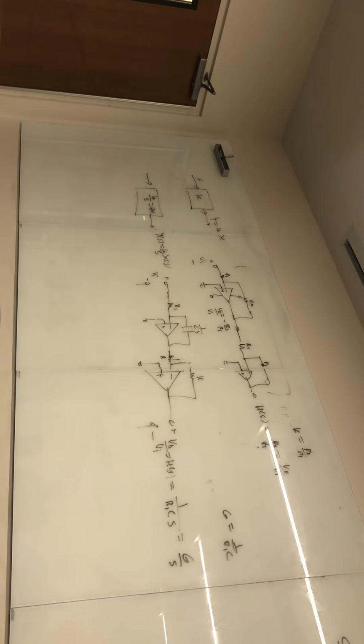Now, I'll manipulate that. I'm going to first multiply top and bottom by S. Remember, I'm trying to get it in the form I understand. So if I multiply by S, I get this. And I get an S here, now I divide by R. And that is typically the low-pass filter's signature for a very simple one. It's got a constant divided by a constant plus S. Now this constant and this constant don't have to be the same; in the one I've shown you they are. Do you all see this?